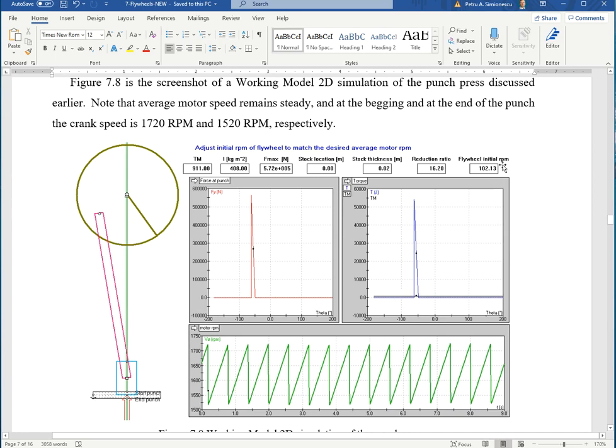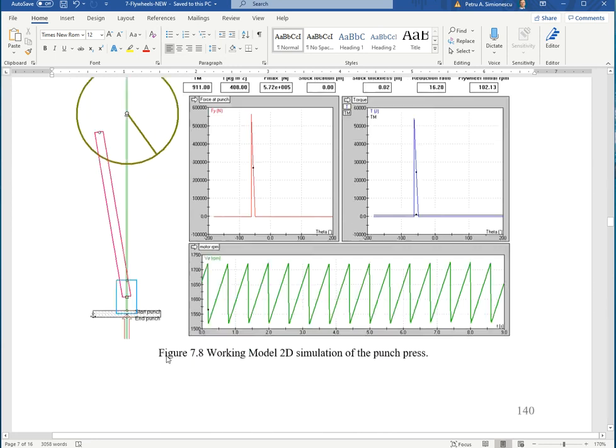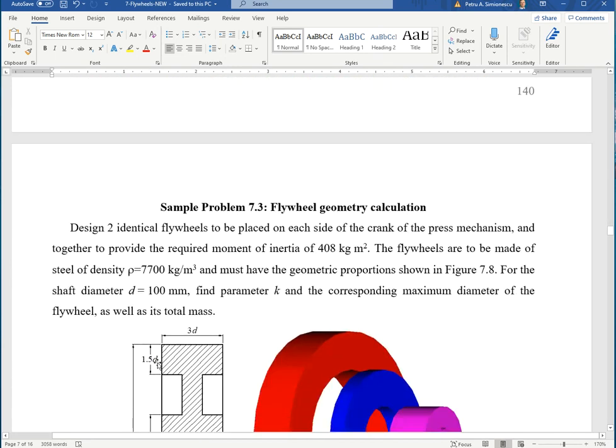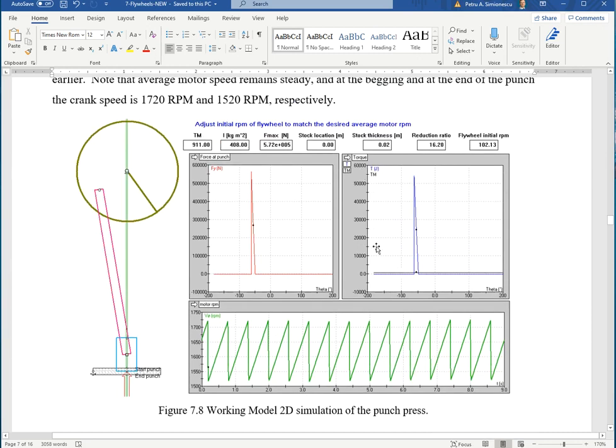Then initial RPM: if you start from 0, it will be the transient at the beginning. Clearly, when you start the press, you let it run for a few seconds to come up to speed, and only then you begin punching. You don't have the workpiece ready to punch and then flip the switch. That may or may not work depending on the load. You may stall the equipment. And we're going to discuss this specific to the project.